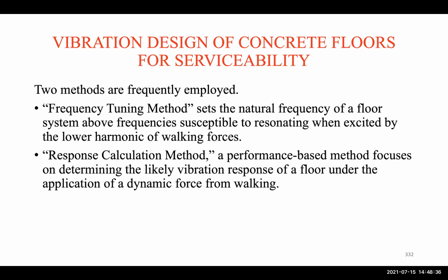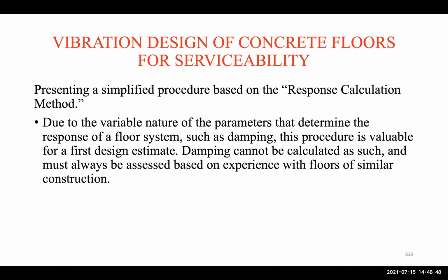And then there is the response calculation method, which is a performance-based method, focusing on determining the likely vibration response of a floor under the application of a dynamic force of walking. So here we can present a simplified procedure, which is the response calculation method.